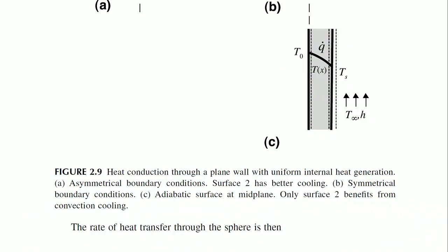The moment you keep it in close contact, and then you also reduce the thickness of the plastic enclosure, you have beautiful conduction across both the surfaces and an amount of cooling is possible. The second part is where your creativity is required, after you understand the rate at which things cool and all that, it is very much possible for you